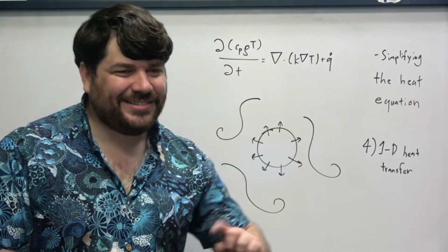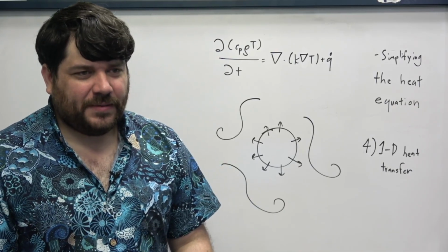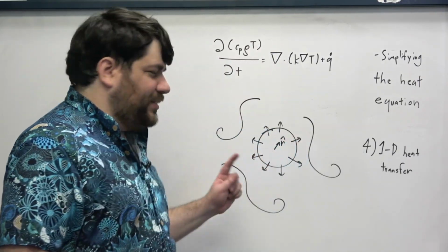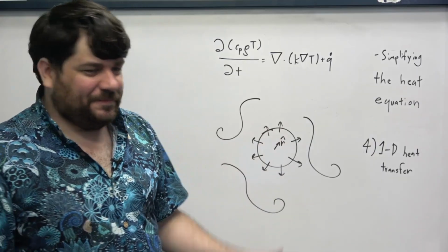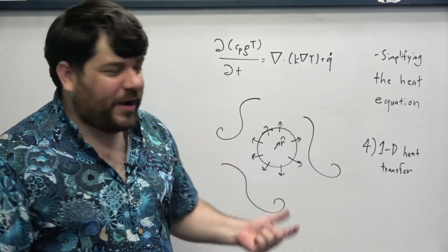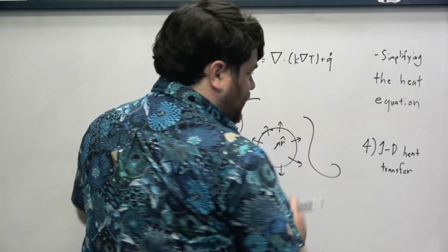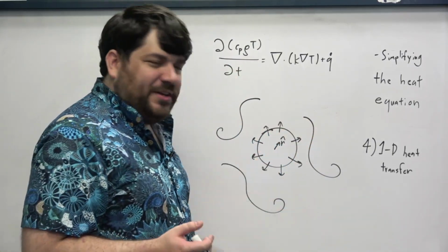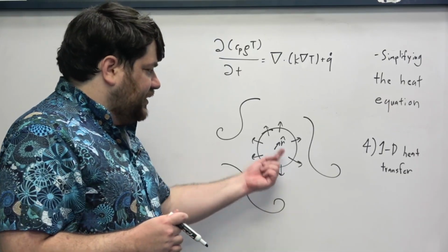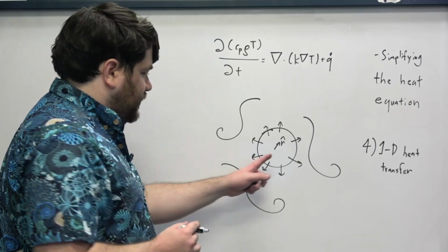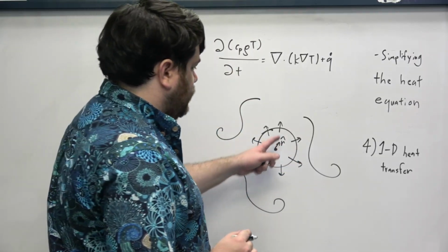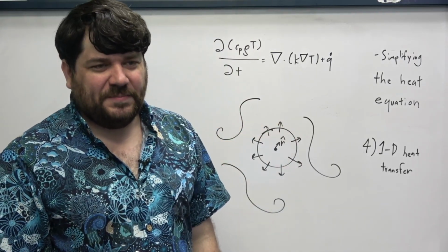Okay, so not necessarily in a single direction, but if we define a radially outward direction, then at all points the heat transfer we can approximate is occurring either this way or this way. And so this is still technically one-dimensional heat transfer, right? Because there's only one dimension, there's only one piece of information that will tell us how this can change, which is the distance from this central point to wherever it is that we're analyzing, okay?